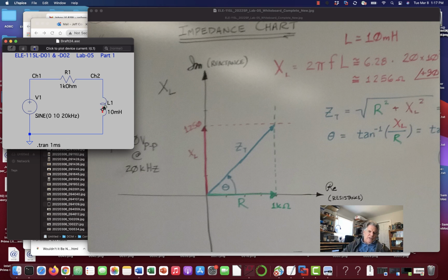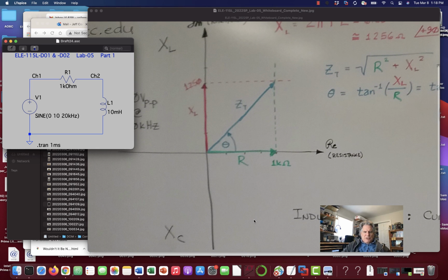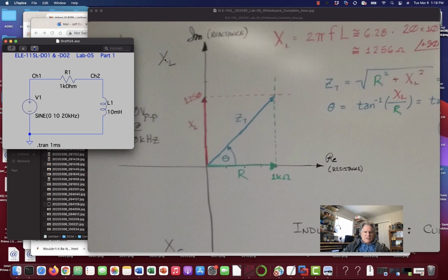I go back and look at my inductor, and I know that I need to get the AC resistance of this inductor, if you will, or its inductive reactance. And we'll make a graph, and I'll show you that in this graph, if we had capacitive reactance, we would compute it with a formula, and it would point down here at minus 90 degrees, and inductors, we compute their reactance and we put it at plus 90 degrees. And then we take a vector sum of these two quantities. Okay.